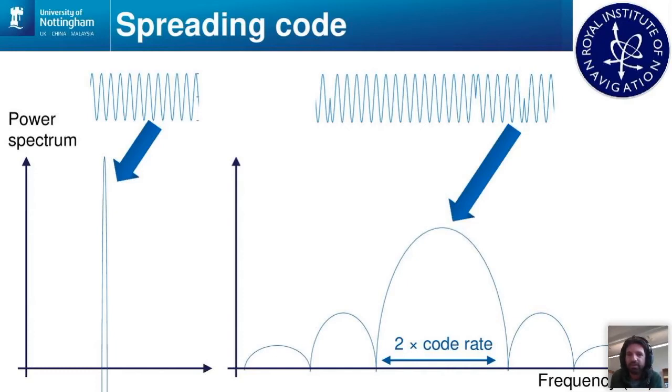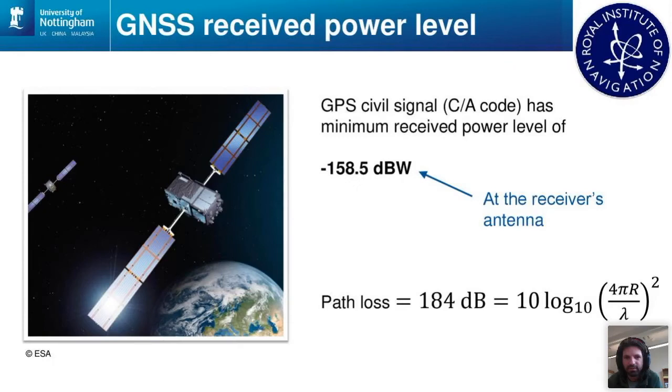So generally, like in the case of the normal GPS signal that we're used to picking up, we'd have 1,540 cycles of the carrier for every one of these bit transitions, or the code transitions. But this way, we can see it a lot easier. Okay, so that's what the signal looks like, and we can see there the effect of the spreading code.